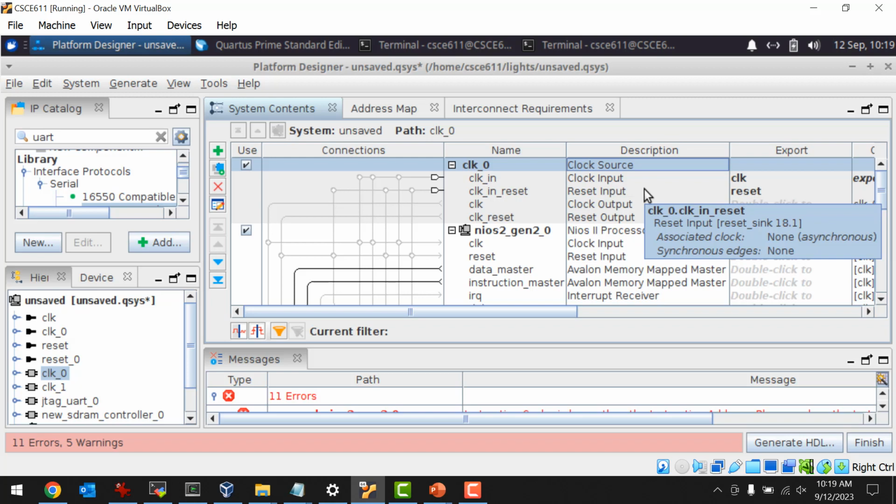And then you have to take that clock pin and connect it to another module that's called a phase lock loop. It's an analog circuit that takes a reference clock as an input, and then it can multiply the frequency, divide the frequency, and change the phase shift of that clock. And that's what we need. It cleans it up too, because the input clock is coming straight in from a piezoelectric crystal. So on the board, there's a crystal, and crystals are pretty easily recognizable because, for whatever reason, they're always housed in an aluminum or silver colored chip.